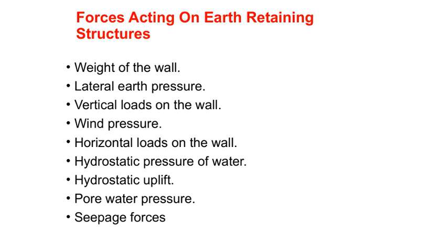Now, water-related forces are particularly significant. Hydrostatic pressure of water acts against the wall when water is present behind or around the structure, exerting outward force that can undermine stability if not properly managed. Along with hydrostatic pressure, we have hydrostatic uplift, which is the upward force exerted by water beneath the structure, potentially causing buoyancy effects that can lift or destabilize the wall.